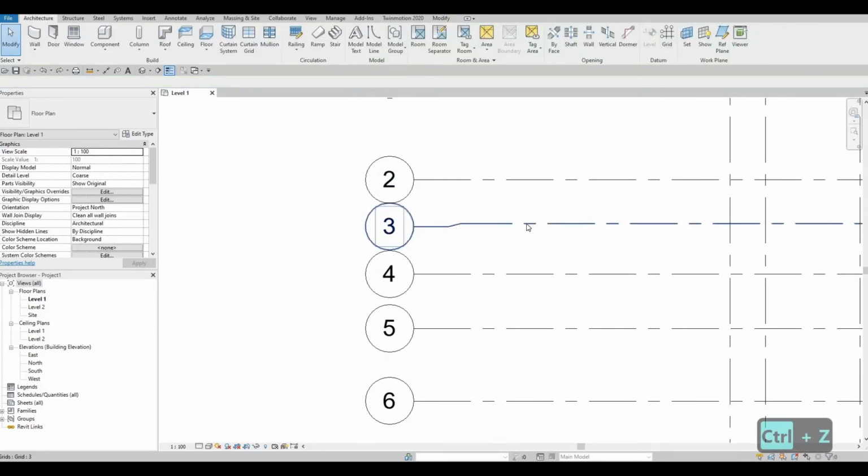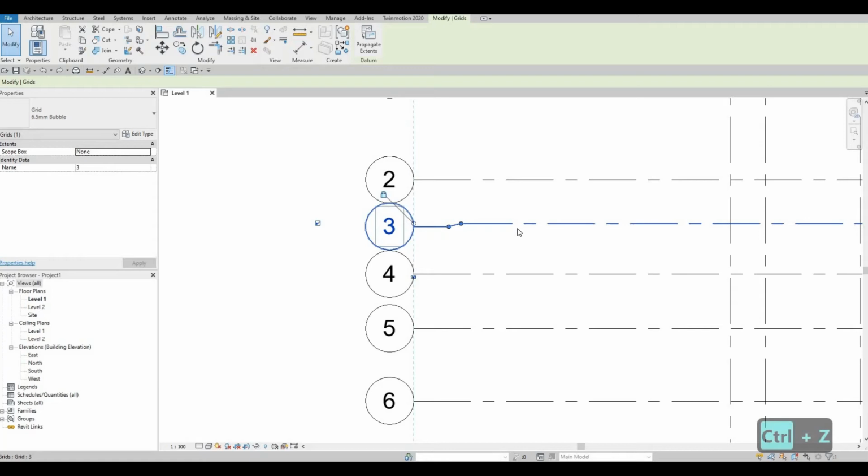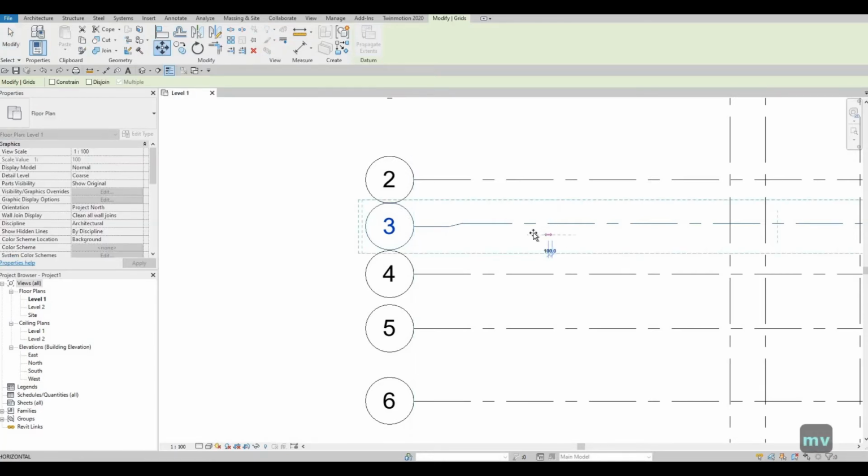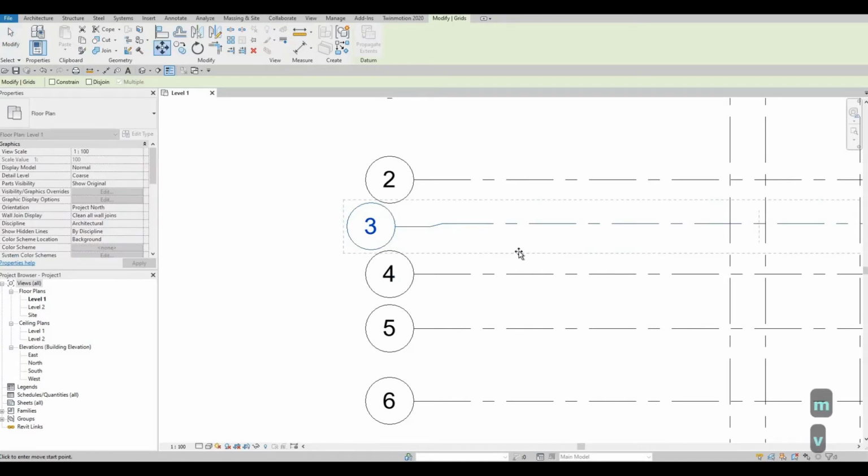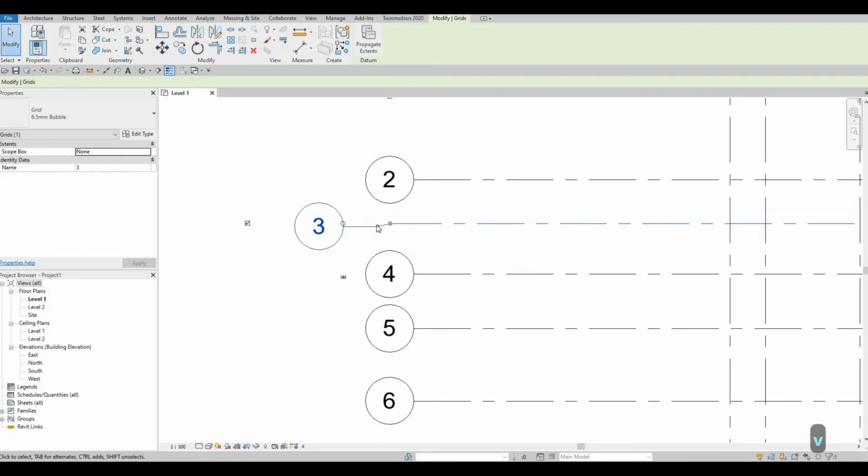So what I do is I just click one of the grid lines, and then I type in MV, or move. So type MV, and then just move it like that. As you can see, it doesn't move everything. So now I'm gonna move it again, MV. I'm gonna drag it all the way out, and as you can see, there's more room now.